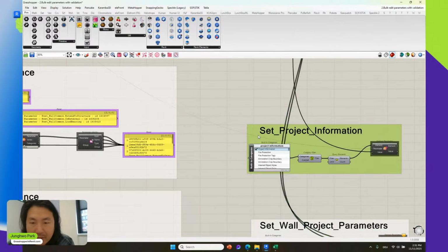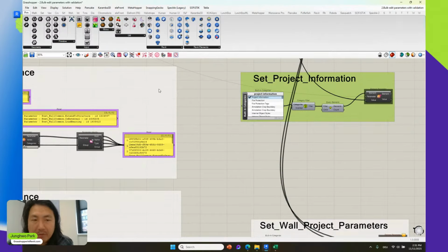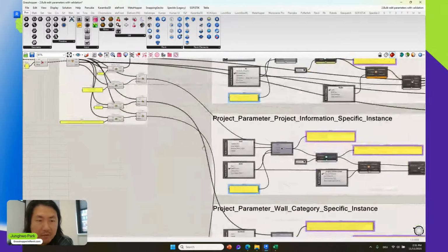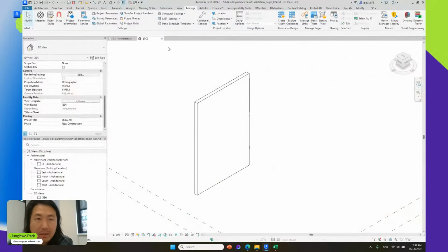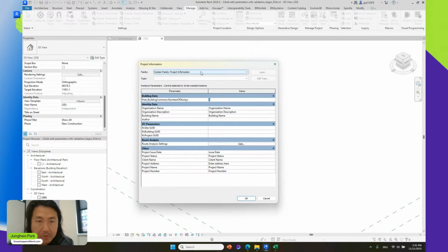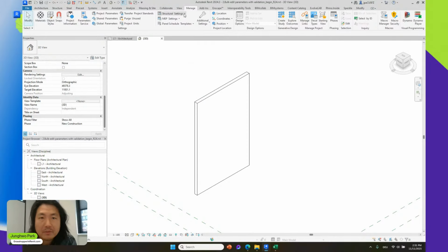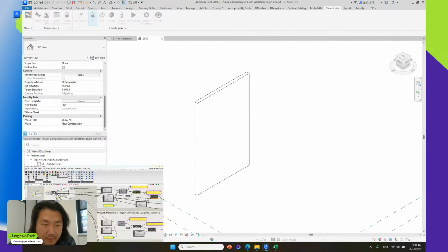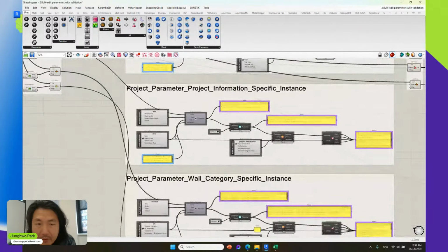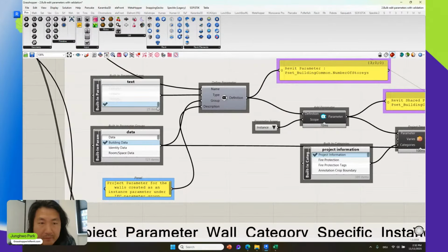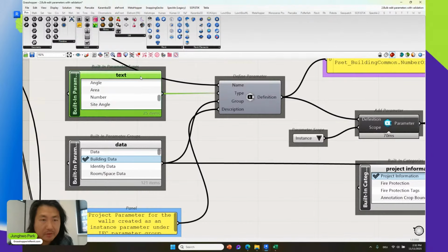And we can not only set element parameter, we can also set the project parameter. So this gets also interesting when we think about project parameter in Revit. If you go to the manage and you have project information, right? And even this kind of information, which is on the project information, we can also provide those kind of information automatically from the Rhino.Inside Revit components. For instance, if I click Rhino.Inside and click Grasshopper, and here we define project, in this case, text is empty, sorry.